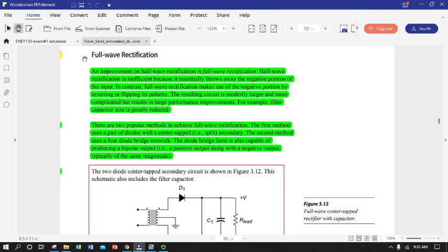And in our last lecture we dealt with diode use for half-wave rectification. So we looked at using the one-way current flow capability of a diode to take just the upper, or depending on how we orient it in the circuit, just the lower half of a periodic, neutrally, a no DC offset periodic waveform. And then we looked at ways to smooth that out and give us closer to true DC using a capacitor in parallel with our load.